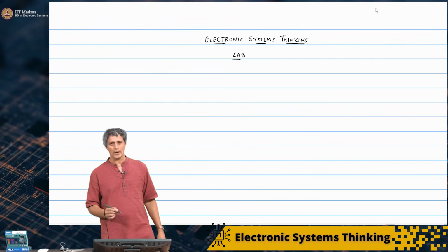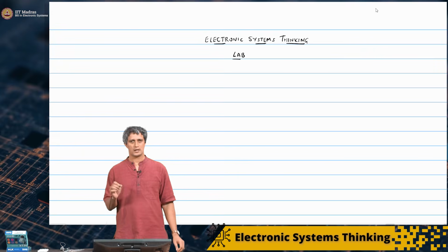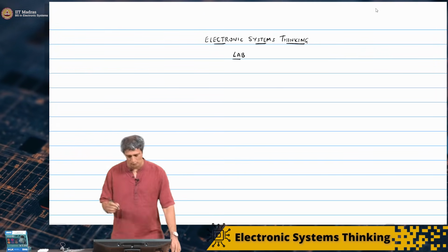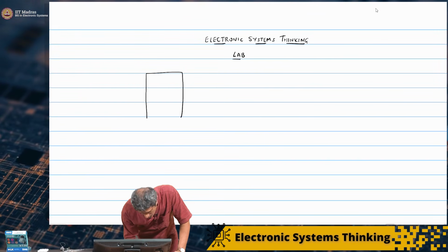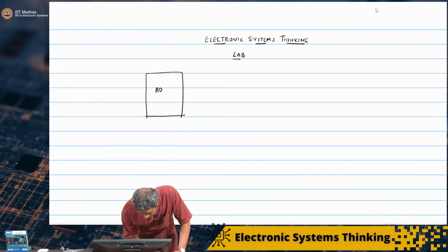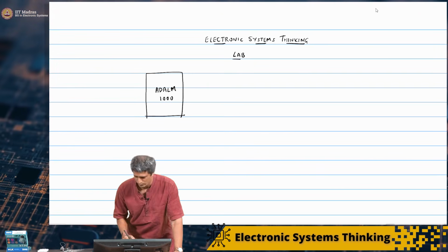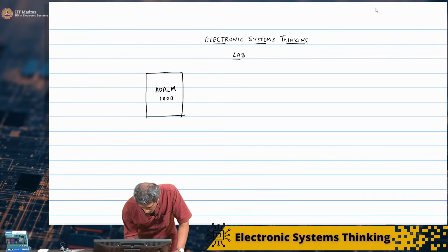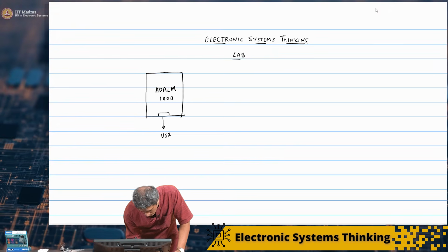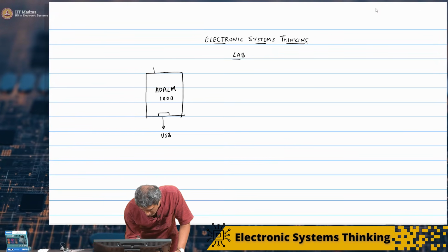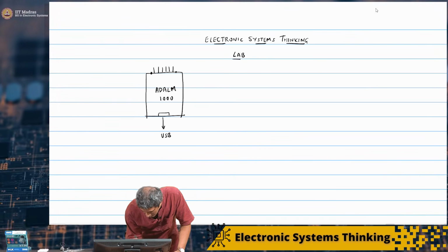Now what we are going to do is simply connect a low pass filter to this kit and observe the waveform. What we have first of all is this ADALM1000 kit. This is the USB, and here is where we have these header pins 1, 2, 3, 4, 5, 6. Now 7 and 8 are not used.